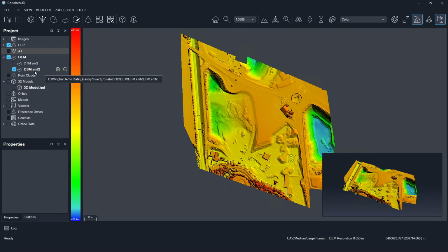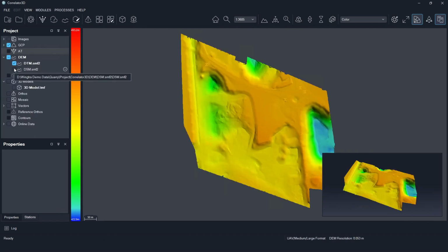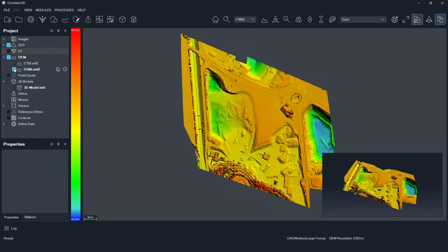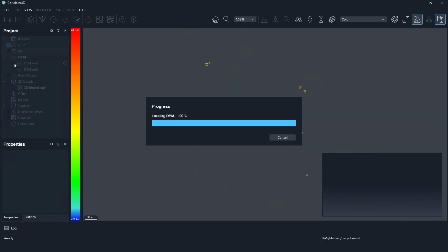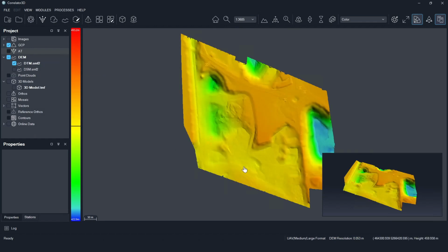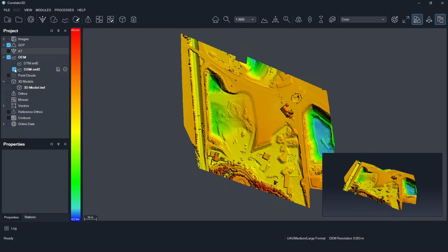So that's there. Obviously, the DTM was produced from that as well. And we can take a look at that. There's the DTM, nothing special there. What I would like to say is that in this conversation, we're talking about quarries and volumes. You're probably going to want to do your volumes from the DSM. And that's because the job of creating the DTM is to eliminate features such as buildings, cars, trees, those kind of things. And we'll look at it and you can see they've been eliminated in these areas. You don't see those buildings anymore, anything like that. But we'll go back to the DSM.